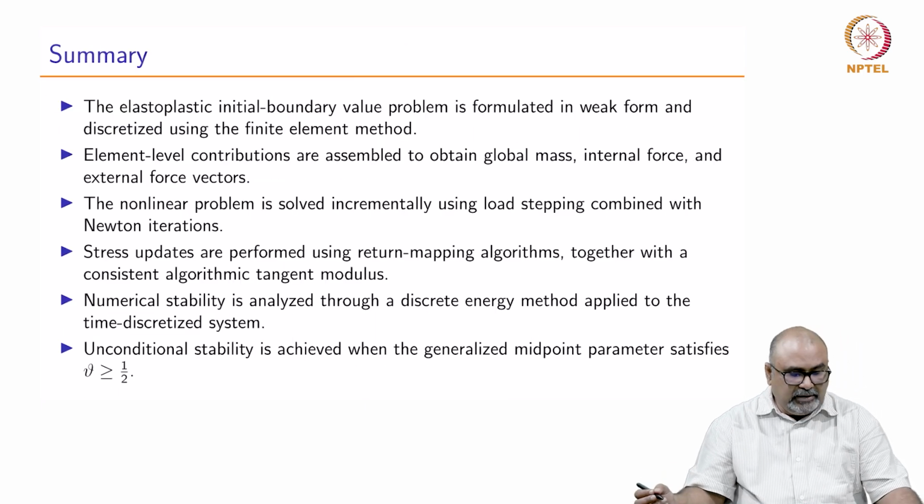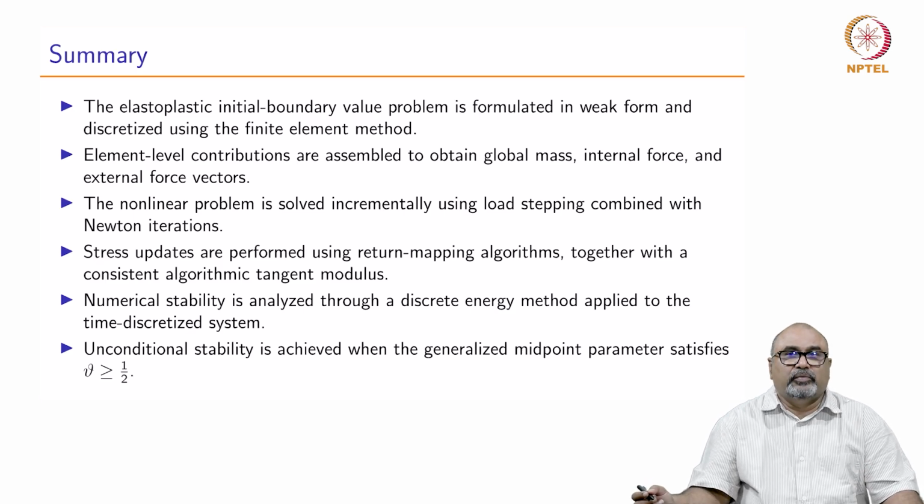Now, in summary, in this lecture we have looked at the elastic plastic boundary value problem and formulated it using a weak form approach, and understood how to calculate the element level internal force and external force.